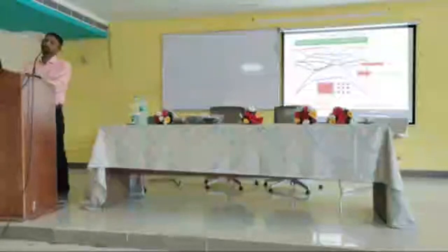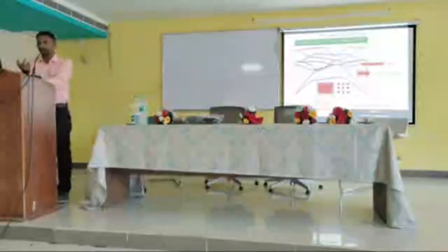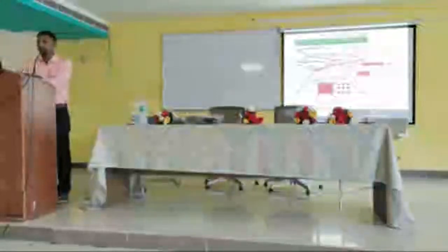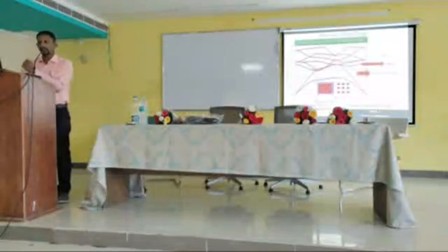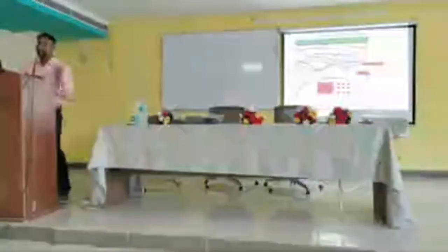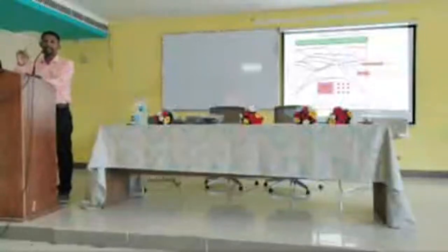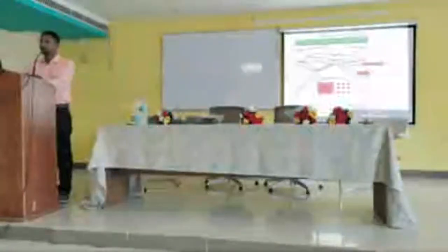Correspondingly, since the structure is periodic, we estimated the band diagram for the smallest area, which represents the entire area, the smallest Brillouin zone. So we have calculated the PBG for the 3 cross 3 lattice. Here there are 2 modes. One is the TE mode, indicated in blue. The TM mode is indicated in red. It is a deeply etched pillar or rod type, hence it is responsible for TE mode. Hence there is a PBG for TE polarization.